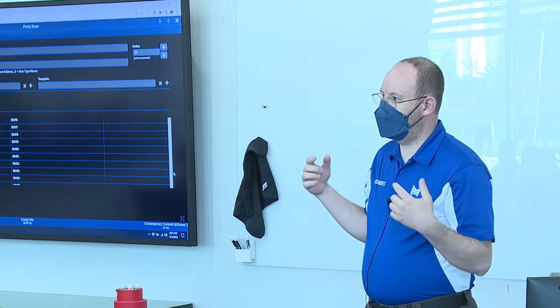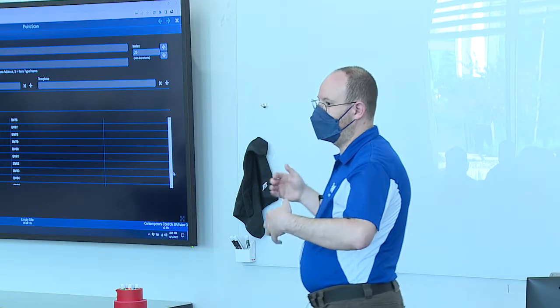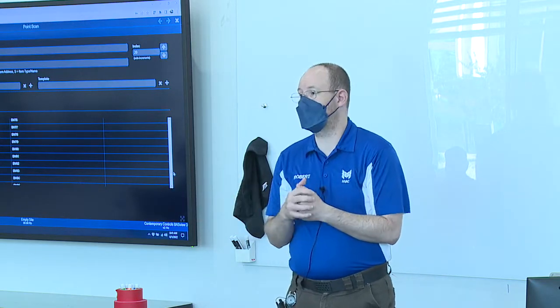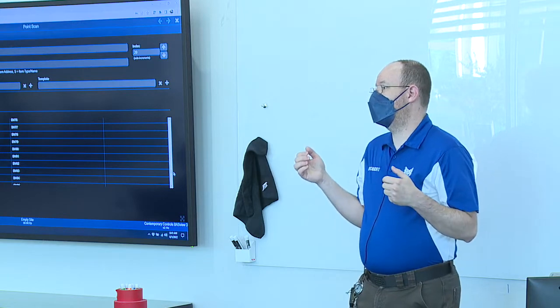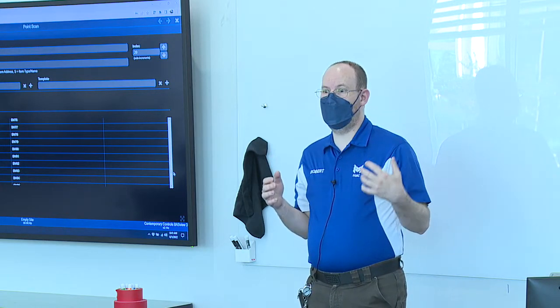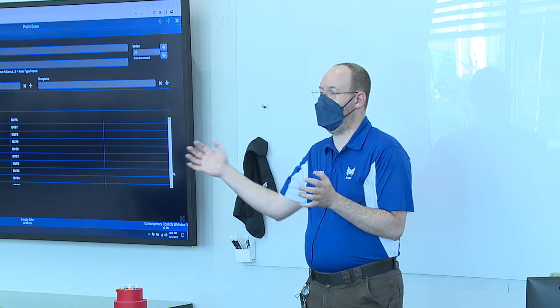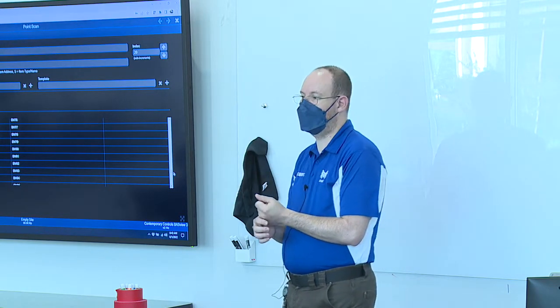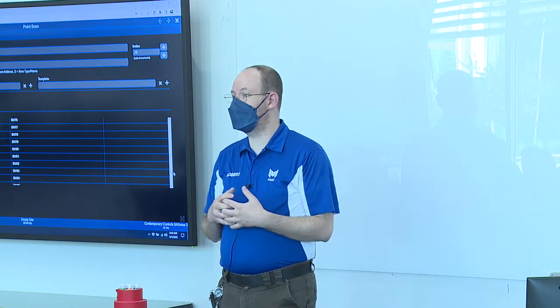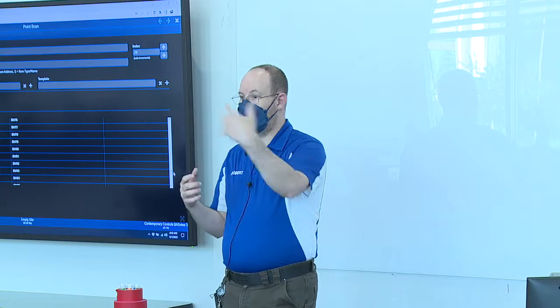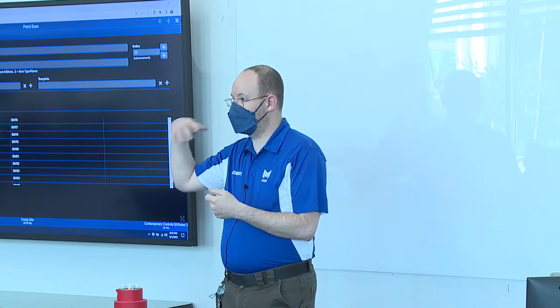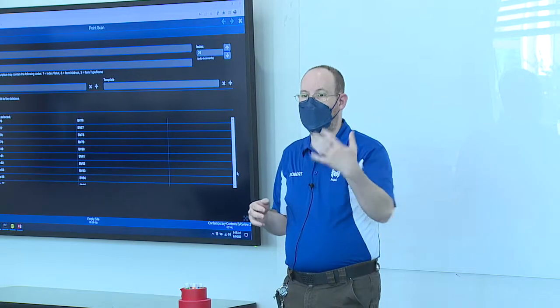Now, this is going to be something that is heavily flavored by my experience in the field. Many companies don't actually use anything close to all of the BACnet objects. Especially if it's a fully programmable system like EasyIO or Johnson or Schneider, ALC.